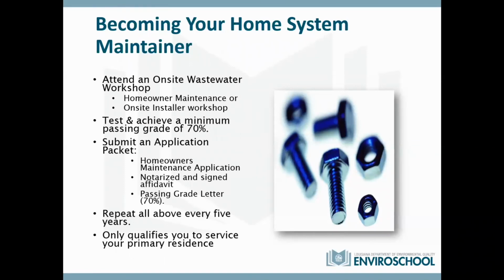However, when it comes to the general maintenance, like looking at your filters, becoming familiar with your system, watching what goes into your system, not pouring stuff, checking your effluent, looking to see if your blower is still working, all that kind of stuff, everybody has to do that.